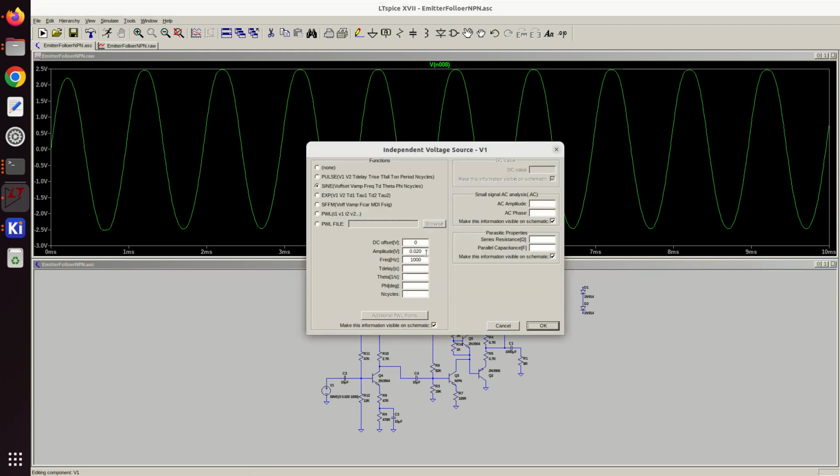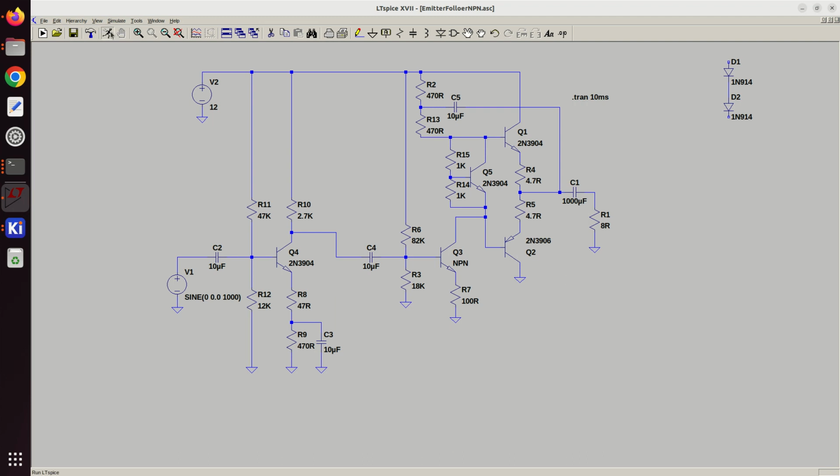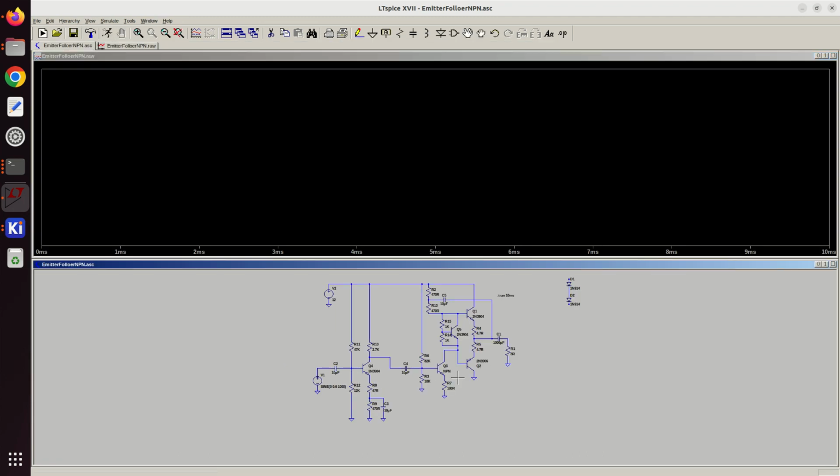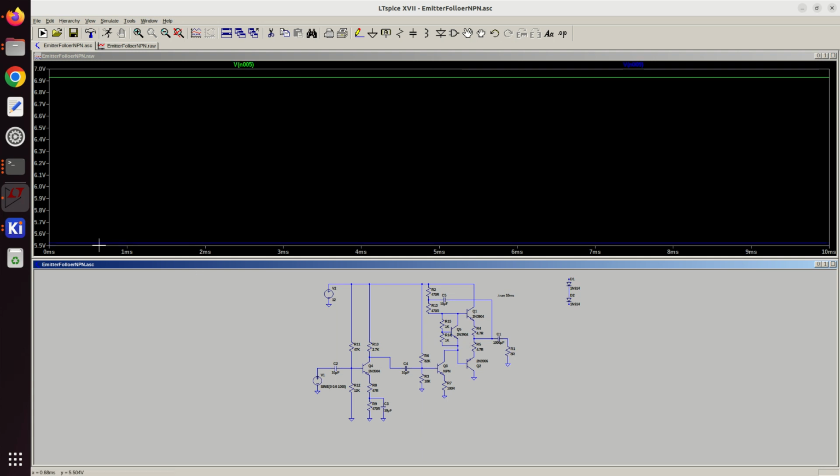Now let's start looking at the DC voltages here again. So we know we've 12 volts here. So what have we got here? 6.93, and then at this side we have 5.5. So if we add in 1.4, that is the difference between the two of these.